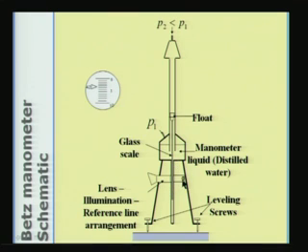And what I will do is use a lamp and two lenses here, and using the eye I can focus on the scale. I can put a spot on the scale, that is the spot I have talked about. And you have a vernier which will indicate the value of the height. In this case I have simply shown 42 point 3 or 4. So, this is so many millimeters or units of water column.